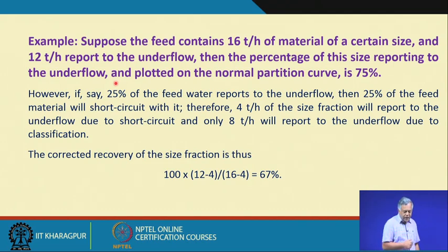So, what is the percentage of feed material reporting to the underflow? That is 12 by 16 into 100, which gives you 75%.